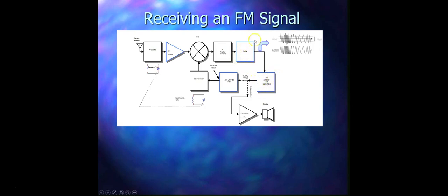Now let's talk about the limiter. Ideally in frequency modulation, you know that the carrier wave amplitude remains constant, which means that the transmitter does not amplitude modulate the carrier, and the envelope carries no information. However, between the transmitter and the receiver, there are various sources of external noise, such as atmospheric noise or man-made noise sources. When these noises are added at random to the voltage of the FM signal envelope, the signal at the output will look something like this, which you see here.